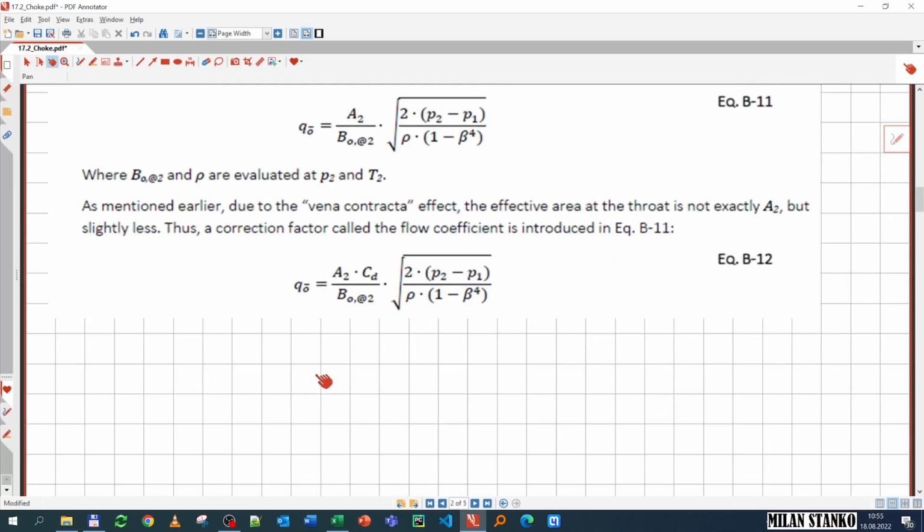So you see the shape of this equation. It's essentially that the delta P, which is what is inside here, the square root, is going to be equal to a constant times QO of the liquid at standard conditions squared. So that equation is what I can use for many orifices, many restrictions. For example, for inflow, I sometimes use that equation.